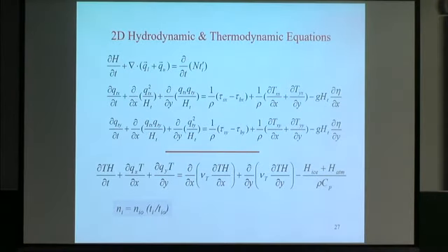Now, to model it, I just want to show the hydrodynamic equation. It's a two-dimensional hydrodynamic equation. Everyone working on river ice or rivers knows that we need roughness of the flow or flow resistance. And when we started modeling the ice dynamics, we said, well, we think the ice roughness is proportional to the thickness.